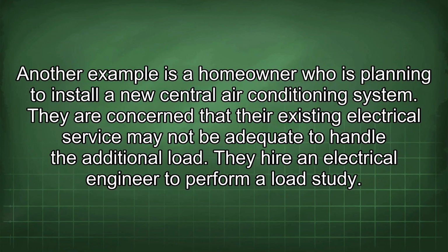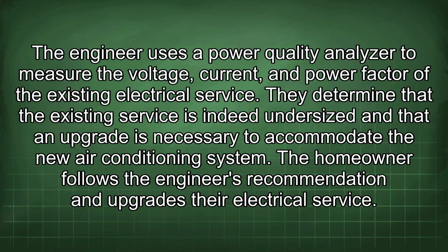Another example is a homeowner who is planning to install a new central air conditioning system. They are concerned that their existing electrical service may not be adequate to handle the additional load. They hire an electrical engineer to perform a load study. The engineer uses a power quality analyzer to measure the voltage, current, and power factor of the existing electrical service.